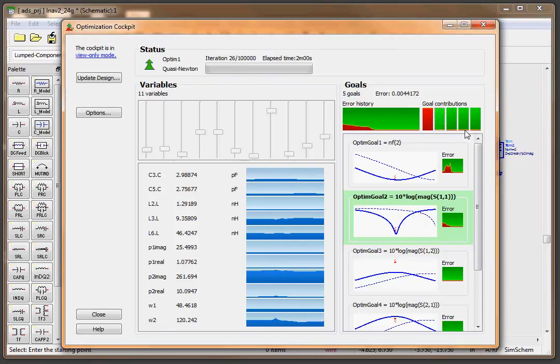At this point, you can see up here, really the only parameter it hasn't matched yet is the noise factor, and it's going to keep messing with it. Unfortunately, sometimes if you gave it unrealistic goals or it's just not feasible, eventually, rather than just iterating 100,000 times, it'll give you a note up here that says like no further improvement possible. In that case, I've just manually tuned some values and started it again. Like I said earlier, this is the quasi-Newton approach. I've had good luck with it. The least pth one worked well for me as well. So much better than the random guessing that you can do as well.